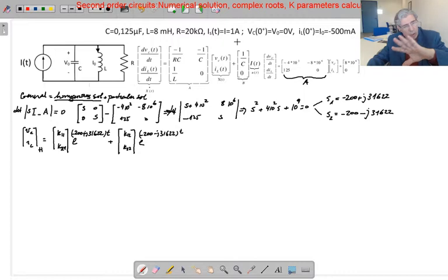You could do it in mathematics in a different way, but let's do it here for this special case by using circuit theory. So VL is L times di over dt. Particular solution is going to be constant since the source is constant. Derivative of it is 0. That means VL equals 0. That means short circuit.